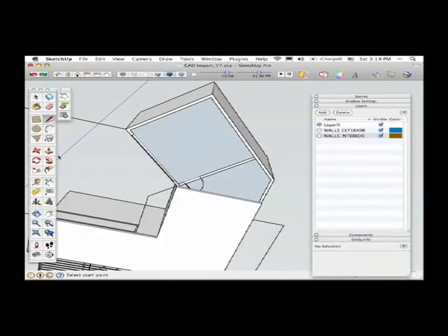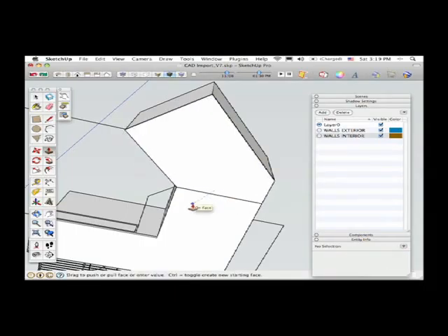The reason I don't like using the pencil tool is it's sort of a just in case kind of thing. Just in case the plan that I've brought into SketchUp isn't aligned perfectly to the axes, if I use the pencil tool to trace over it, I'm inheriting all of those misalignments. I'd prefer to use tools like the rectangle tool and push-pull, which will guarantee that the objects in the SketchUp drawing are drawn to the proper alignment, so they're drawn according to the axes in the model. Using the rectangle tool and push-pull will then sort of compensate for any inaccuracies that there might be in the CAD drawing. In this case, I know that this part of the CAD drawing is accurate, so I can just trace over it with the pencil tool and then use push-pull to get the thickness of that part of the slab.